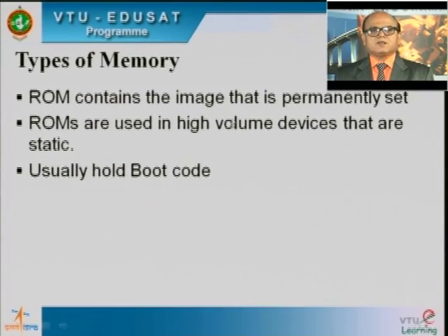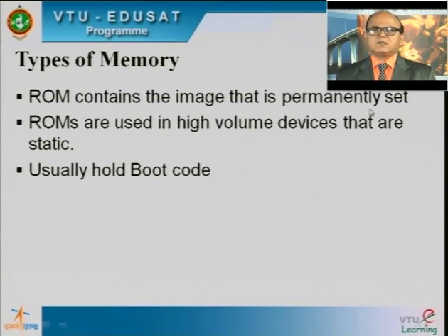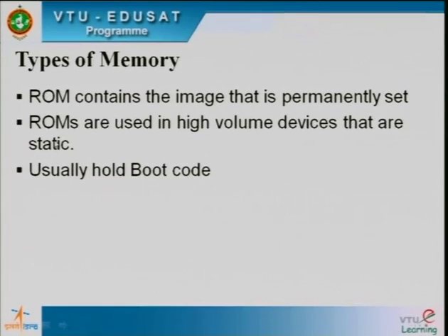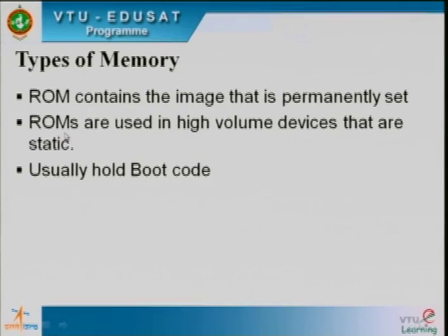It contains the image that is permanently set in the memory, and ROMs are used in high volume devices that are static. That means once I fuse, I cannot modify that. Therefore the code that is static, or will never change in due course of time, data or code can be fused into the ROM at the time of actual manufacturing.